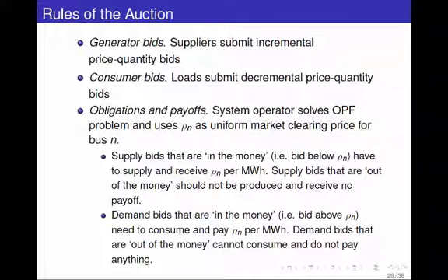Loads submit price quantity pairs, decreasing. Suppliers submit price quantity pairs, increasing. I, the system operator, take them in. Now I don't solve an economic dispatch problem anymore. I solve a more complicated problem, which is the optimal power flow problem.